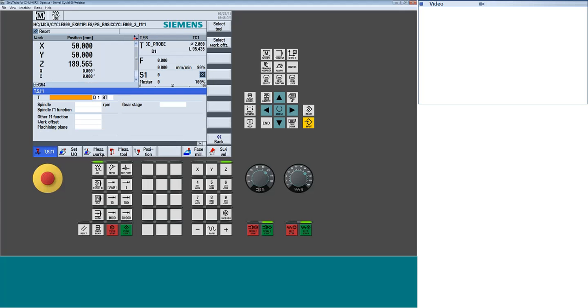I need to initially datum the plane, right? What plane on my rough stock or my part do I want the spindle to be perpendicular to? We call it tool normal. So when I tell the tool to go to its normal position, what is it perpendicular to? Well, a lot of times in the standard system it's going to be perpendicular to the platter of the machine. But what if, in fact, because of the way I'm holding the part, or just the type of feature, I don't want to be normal to the machine's platter? I want to be normal to some face or some compounded surface on the part. Maybe my fixturing's not perfect, and that's okay. We let the machine align to the part instead of having to align everything to the machine.